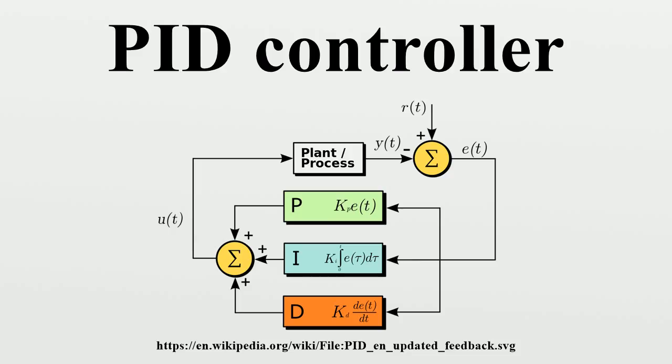Some digital loop controllers offer a self-tuning feature in which very small setpoint changes are sent to the process, allowing the controller itself to calculate optimal tuning values. Other formulas are available to tune the loop according to different performance criteria. Many patented formulas are now embedded within PID tuning software and hardware modules. Advances in automated PID loop tuning software also deliver algorithms for tuning PID loops in a dynamic or non-steady state scenario. The software will model the dynamics of a process through a disturbance, and calculate PID control parameters in response.